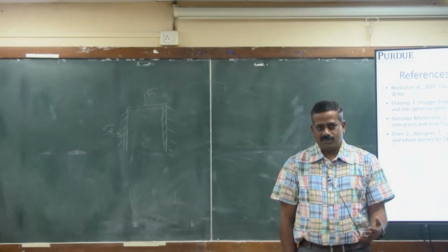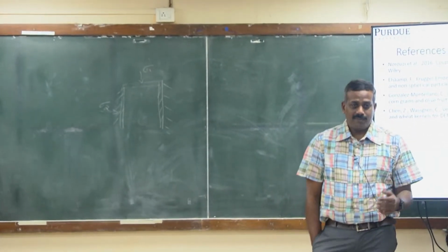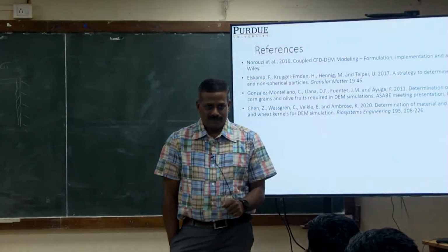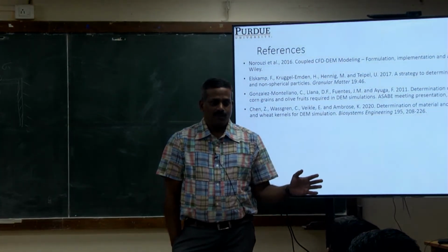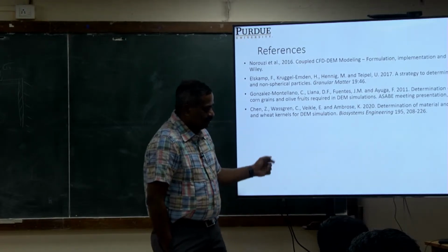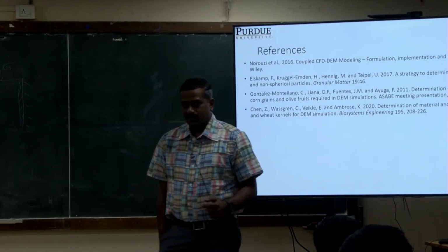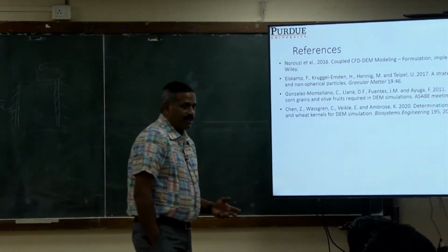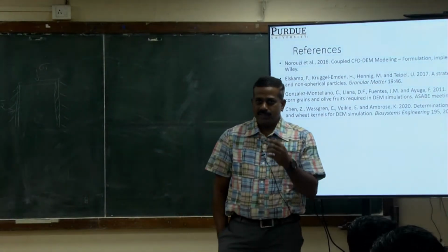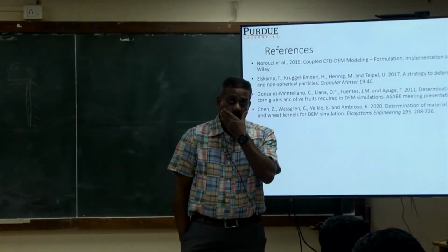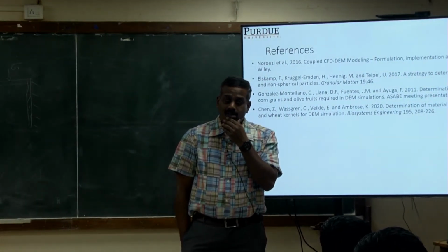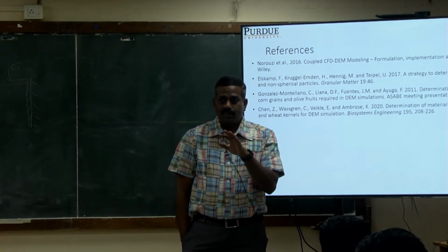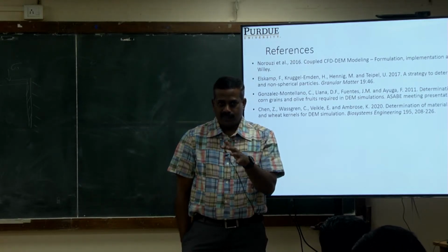So model parameter calibration is also very important and big. They calibrate some of those properties, such as coefficient of restitution and Young's modulus. Young's modulus, maybe you can measure a little bit, not for small materials, but for large materials you can measure. But Young's modulus, coefficient of restitution, Poisson's ratio, etc., are very difficult to measure accurately.